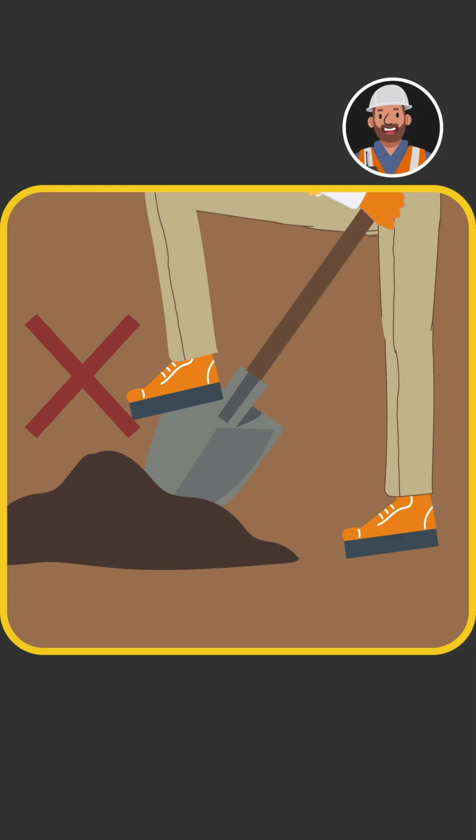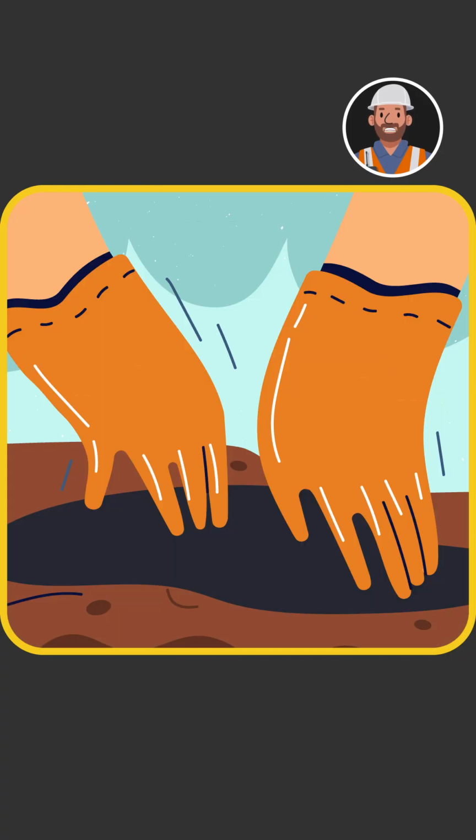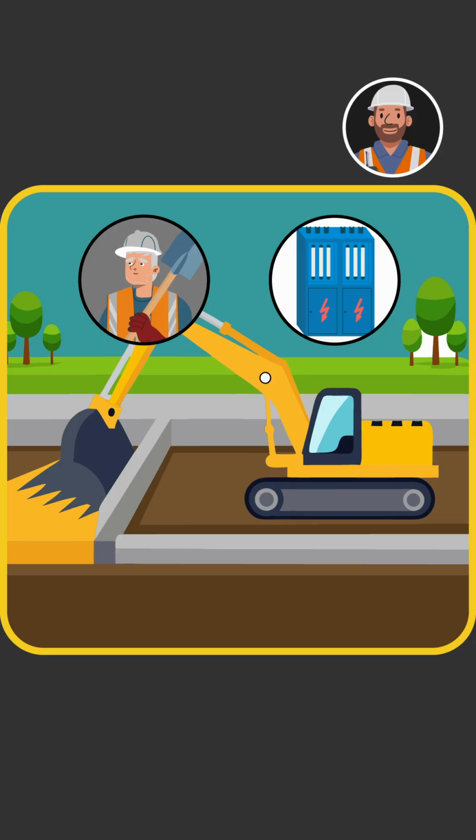If your desktop study indicates there may be a service but it hasn't been located, dig a trial trench by hand to confirm the service's location. Proceed carefully, excavating in shallow layers. Ensure the operator and banksman monitor for evidence of disturbed ground.